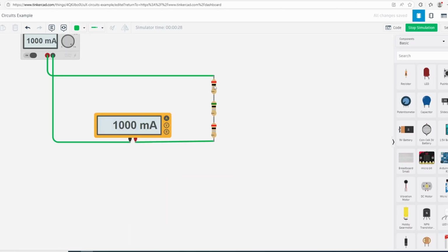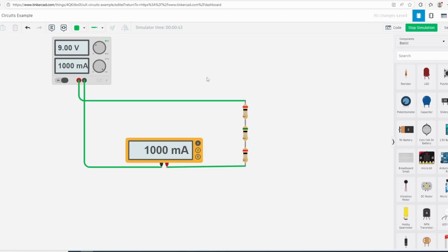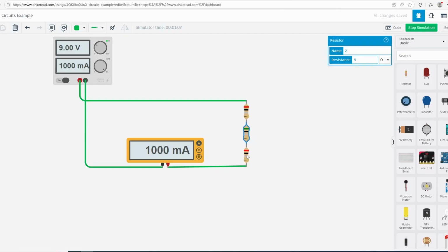And if we were to take these resistors here and take a look at the resistances, 2 ohms, 5 ohms, and 2 ohms, you'll notice that Ohm's law is current, I, which is here, equaling the voltage divided by the resistance. Now, what is that resistance? Well, if you have resistors one after the other in series, then the resistances just add together, which makes sense. So let's add these together. So 2, 5, and 2, that makes 9 ohms.